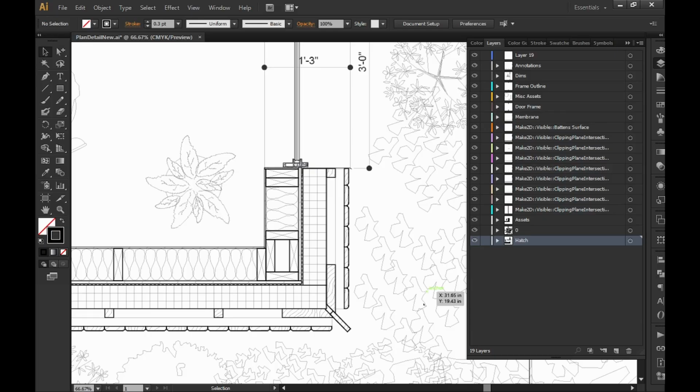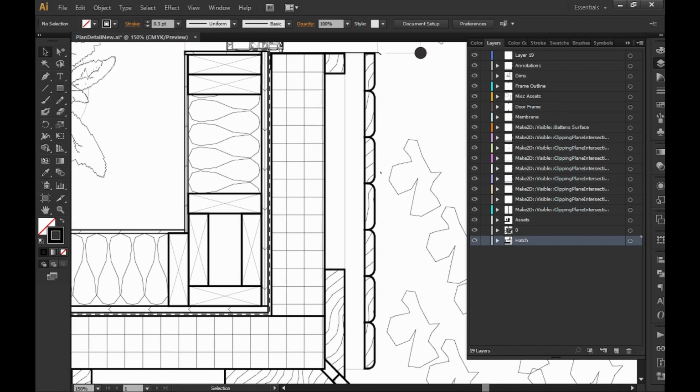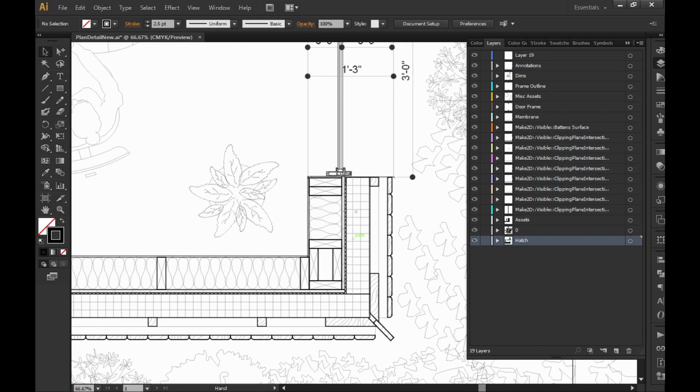Because, for example, this is like a 2.5 or a 3, right? I went ahead and looked at some things. I made this a 2.5 instead of a 3, and I made some things thinner. But it's good to test things out, save it as a PDF or even a high quality JPEG, and see how it looks, to test back and forth on your sheet size. It all depends on the sheet size and the scale.